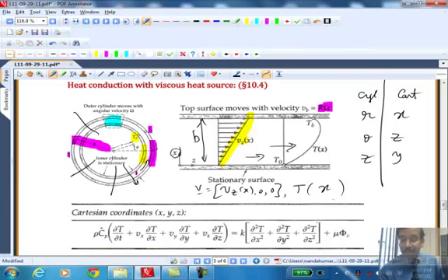Okay, so we already know the velocity profile. The velocity profile is Vz as a function of x. Do you remember what it should be? Vb times x over b. It's a linear profile in the x direction. So at the bottom plate when x equals 0, the velocity is 0. At the top plate when x equals b, the velocity is Vb. So this we already solved, and you should know how to solve that. So we're going to focus on the temperature.